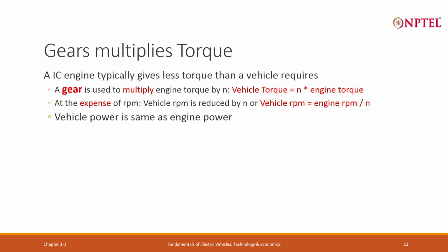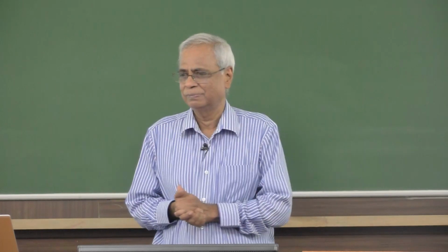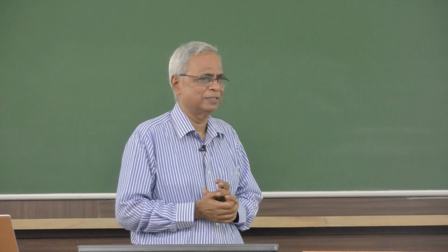Vehicle power is engine power. So, there is no difference between vehicle power and engine power. Torque gets multiplied, rpm gets reduced by the same factor. So, the vehicle power and engine power are the same. You will see the same thing in electric vehicle.